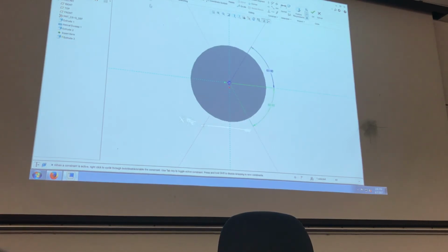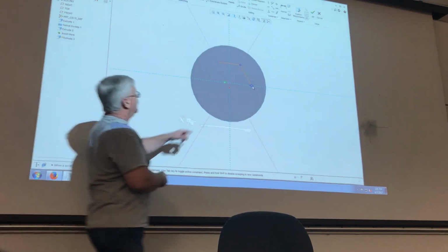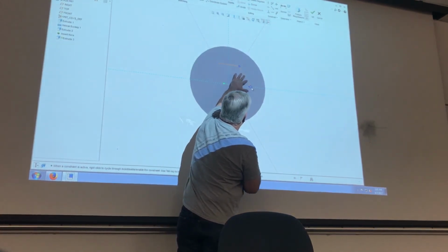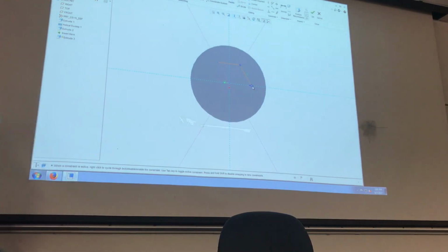Then you're going to take a line, snap it to that point, and you're going to use the constraints on here. The H is horizontal. Snap there. Snap to this line, come across till the parallel line shows up. What that's telling me now is that this line and this line are parallel. So now I click on that one. And then you use these constraints all the way around. So you're making use of the features that Pro-E has in it. So now I've got my shape.